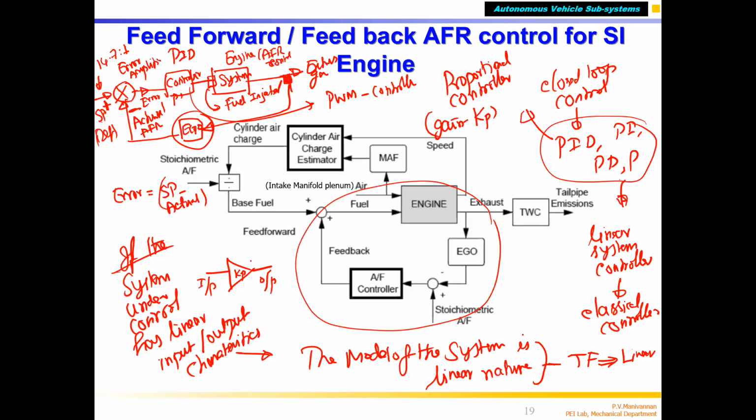For example, if I set Kp equal to 10, and I give an input value of, say, 0.5, what will be my output? The output will be equal to Kp multiplied by input. So it is going to be 10 multiplied by 0.5. The output will be 5. Now if the input is varying from 0 to 1, then the output will vary from 0 to 10.